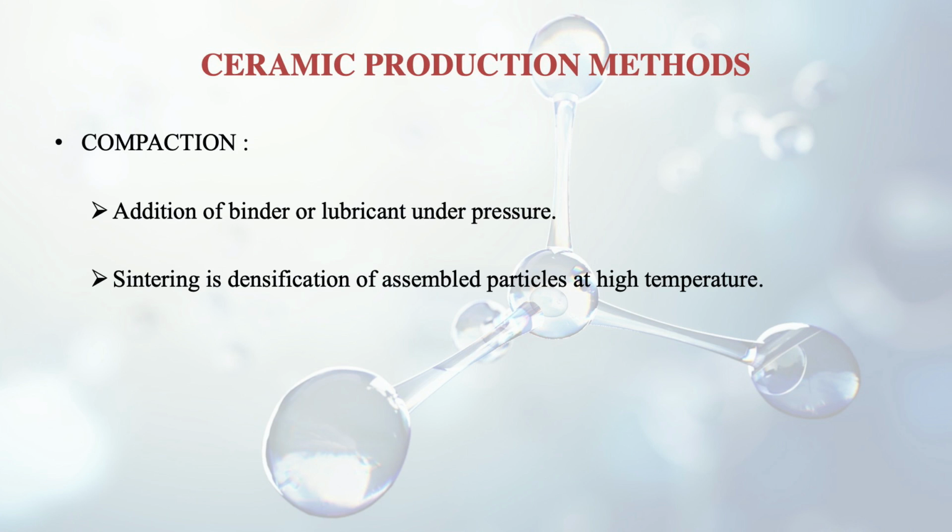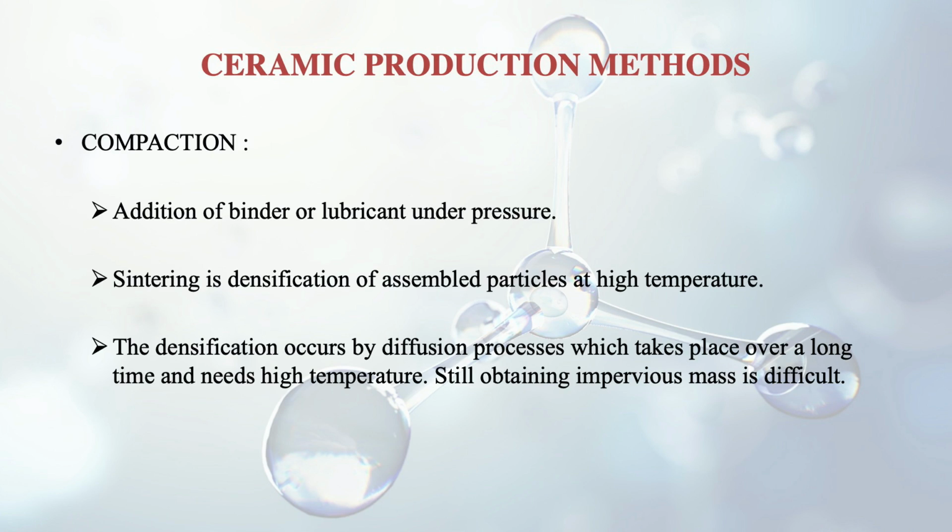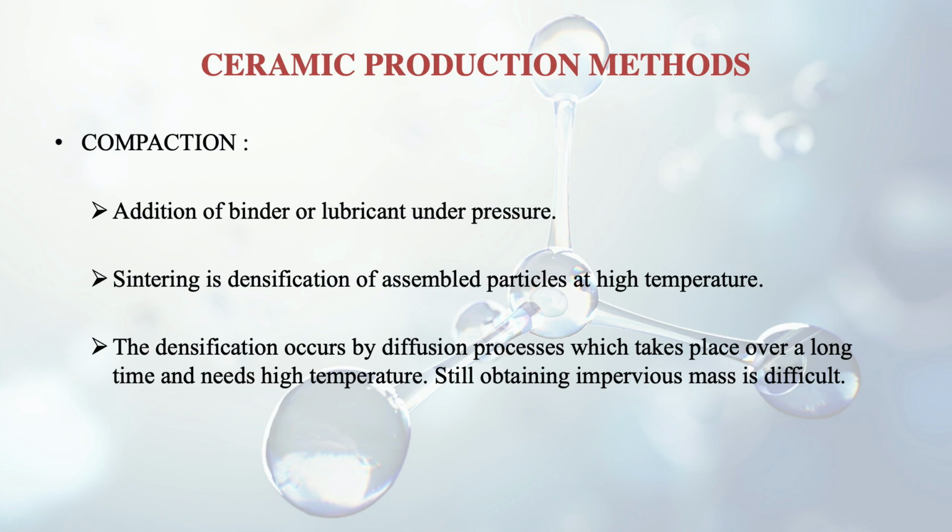Sintering is a kind of densification of assembled particles at high temperatures, meaning we are bringing all the particles together by compressing them with each other. This densification occurs by diffusion processes, which you may have read about in your chemistry subject. Diffusion takes place where the molecules diffuse amongst each other, and this takes place over a long time and needs high temperature. But still, after this diffusion and sintering densification process, getting an impervious mass is very difficult, meaning pores will still be there.